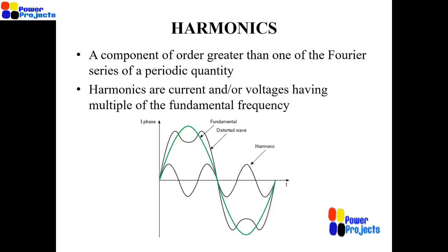Right, harmonics. You have the fundamental and multiples of it, and then the waveform is distorted. With Fourier analysis, the Fourier transform converts any non-sinusoidal but periodic waveform into a summation of sinusoidals and cosinusoidals. That becomes the harmonics, like the second harmonic, third harmonic, etc.